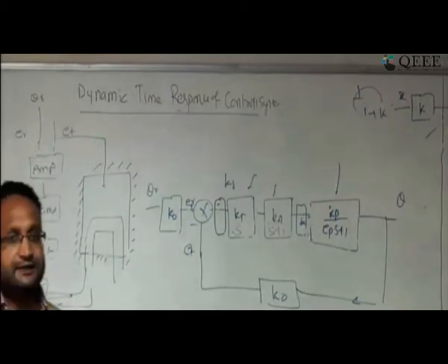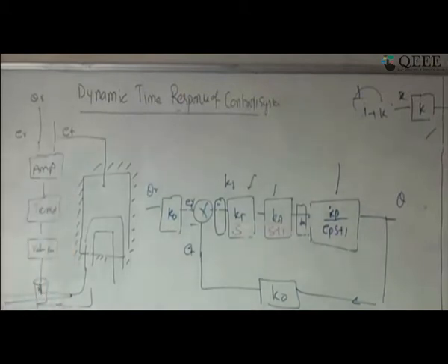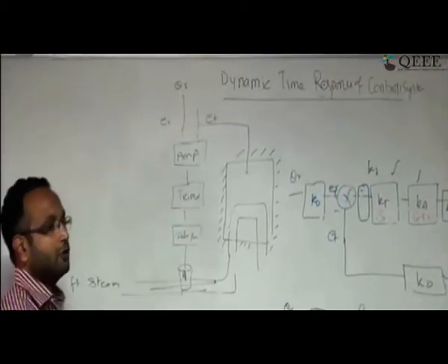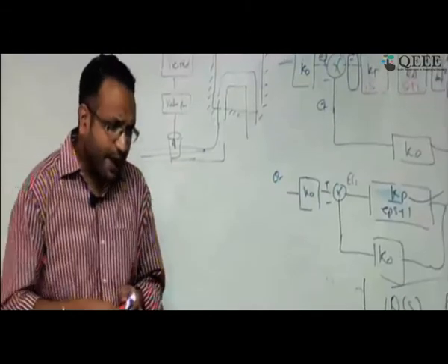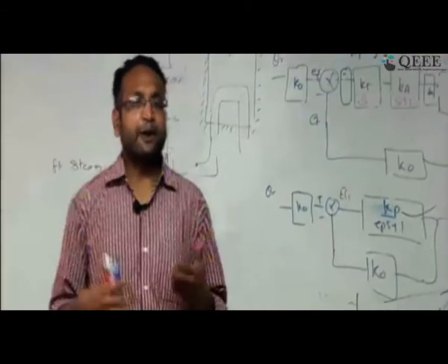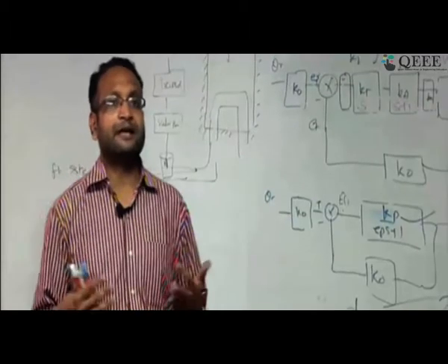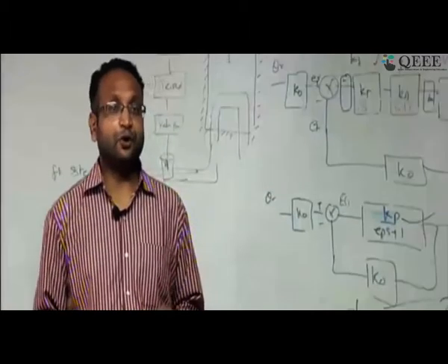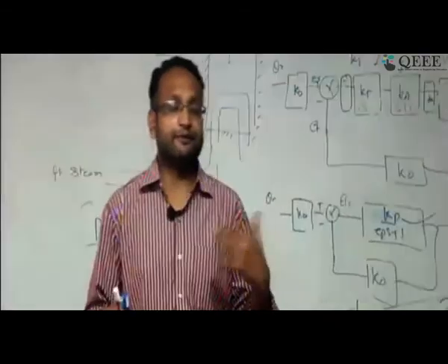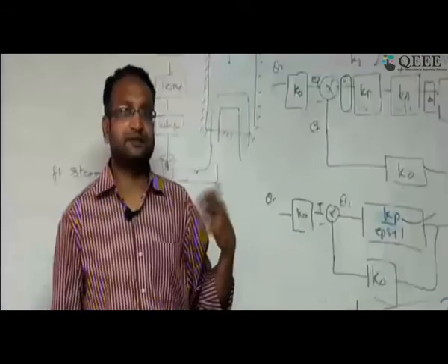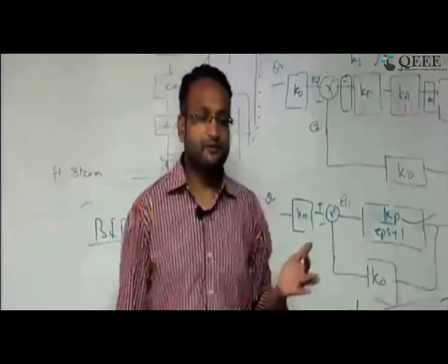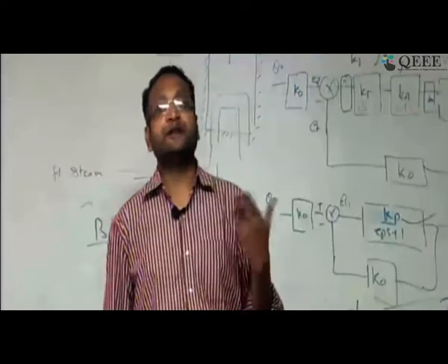Okay. And stability means, if you go slightly, I want to cover, stability is defined as BIBO stability, which means a bounded input will give a bounded output. And if there is a bounded input and it gives an unbounded output, then I say the system is unstable. You give some input, say a sinusoid, and the output is unbounded. It's giving a very high value, so your system will collapse. So that's why you don't want to design a system which is unstable.